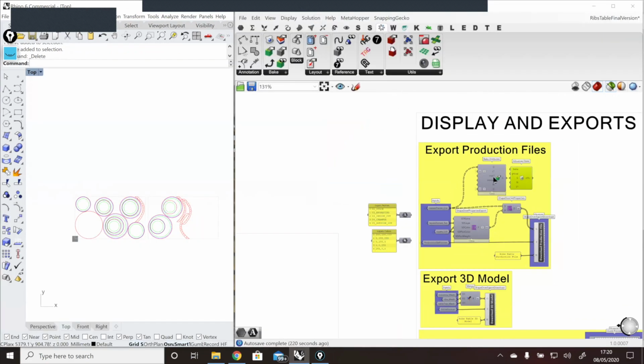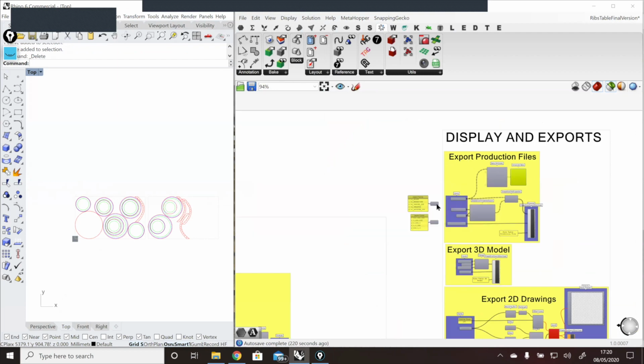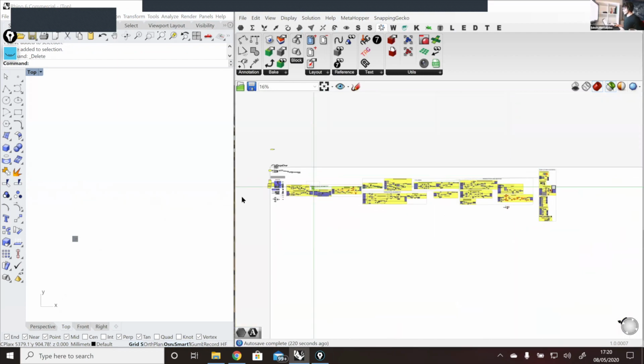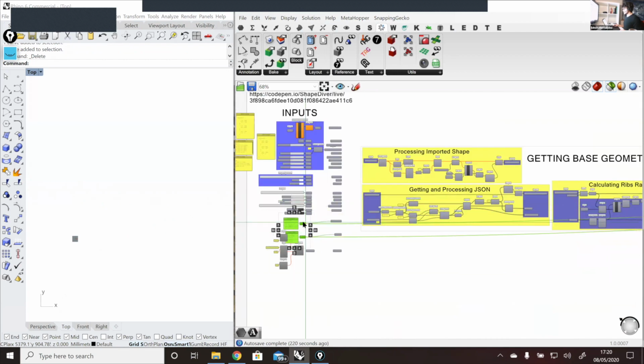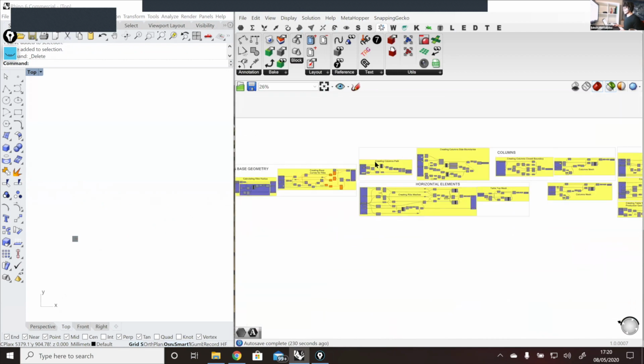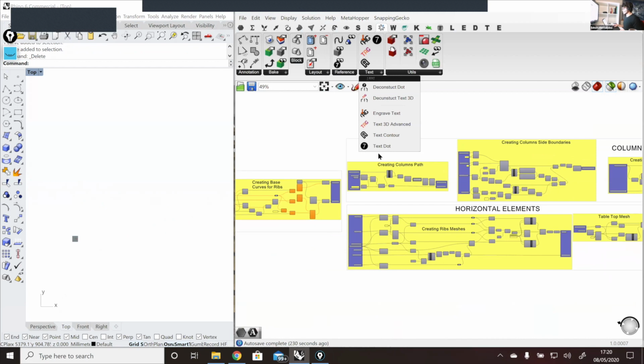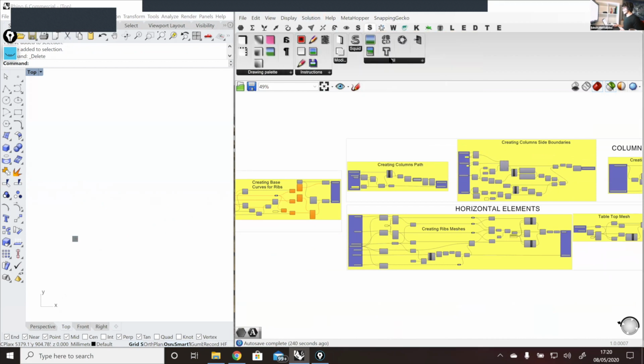Yeah, all good. One question about how you created the number labels for the cut parts. For the labels, there are different plugins that allow you to create text curves from text. For example, FabTools has some of them, like text contour, but also Squid has its own component, the text curves component.